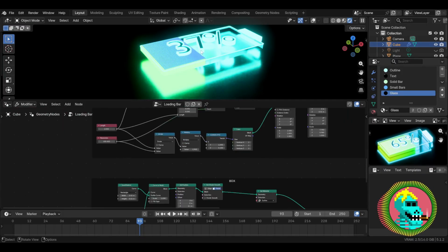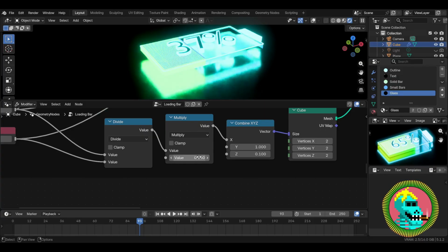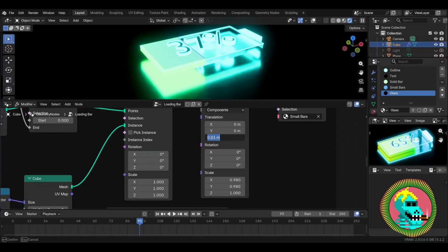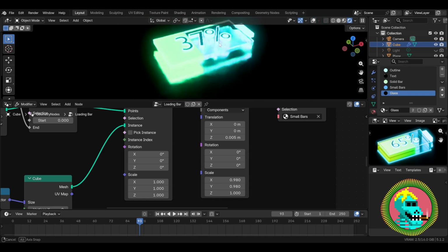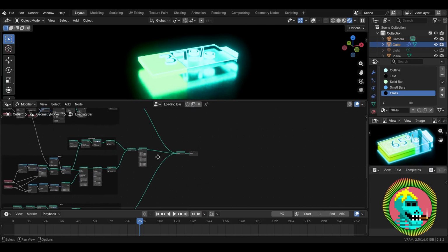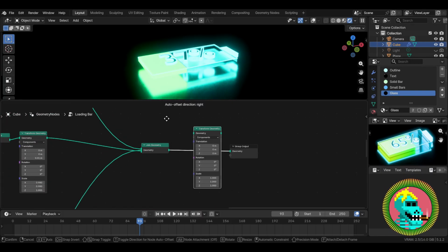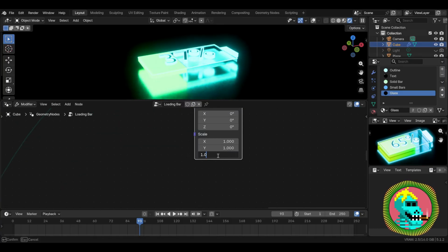Also, to make the stripes less protruding over the surface, let's increase the gap between them by setting the value to 0.1. And also reduce their lift height to 0.005. Now they look more neat. Next, we'll adjust the overall thickness by adding a transform geometry node. And setting the scale value along the z-axis to 1.5 or 2.